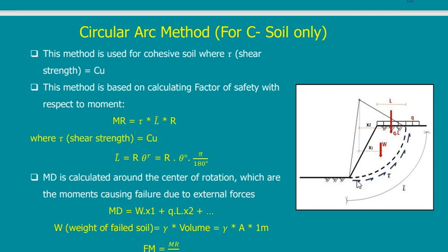The total friction is this small force multiplied by this arm, plus this small force multiplied by this arm, plus this multiplied, and so on till I reach the top. So all of this is the frictional forces that are preventing this portion from sliding.